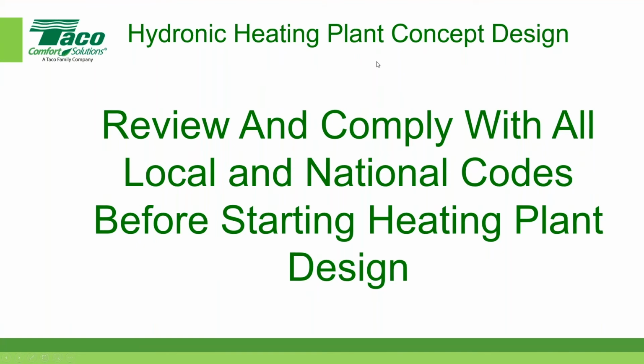so I like to put this up, especially when we're talking about equipment that burns fossil fuel, and that is to say: review and comply with all local and national codes before starting heating plant design. This is extremely important because codes vary throughout the world and there are multiple layers, which is why I put in the phrase national and local. In the United States, there are national codes, there are state codes, and there are county and/or city codes. So there turn out to be 3 or 4 layers of codes that we have to comply with, especially when it comes to fuel burning equipment. So please be aware of the codes before you start designing.